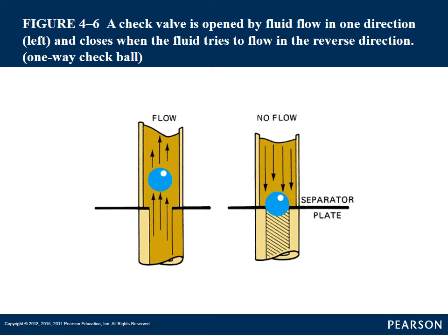Well, there's a smaller hole next to it that the fluid is able to go through, and that smaller hole, when we start talking about orifices in a minute, actually reduces the pressure, so it applies the clutch pack softer. Then when they're done with that clutch pack and they release that pressure, they want to get the fluid pressure to exhaust out of there faster.